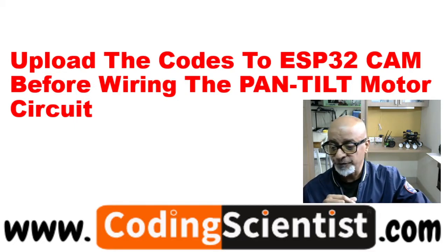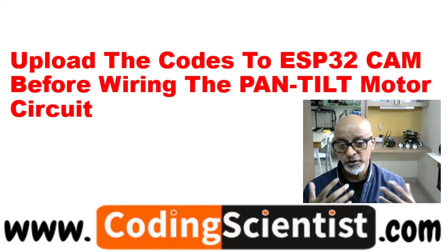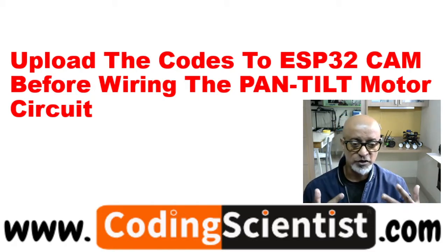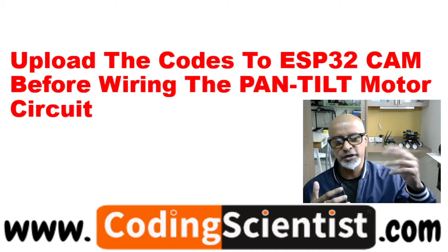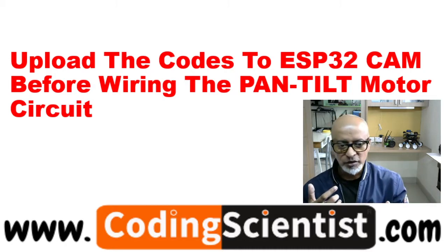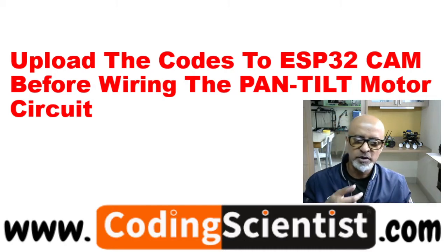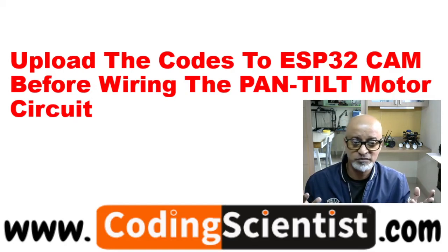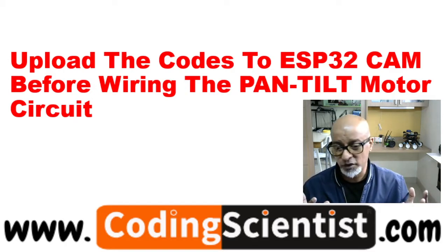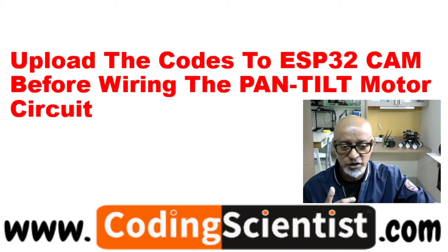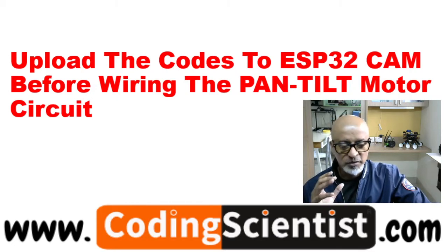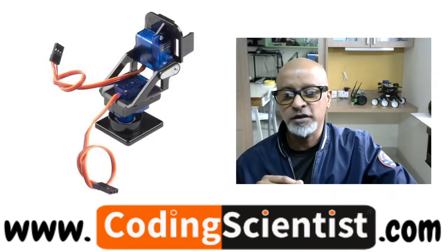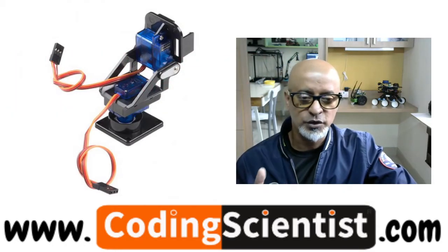All right. The reason is, of course, we will be using two different GPIO pins of the ESP32 CAM to connect your motors. And once you fix it and mount it, you may not be able to reset. That's another challenge, because the reset button is at the bottom of the ESP32 CAM board, which, as per design, is definitely not good, but can't help. That's how it is. So that's the reason. Go ahead and load the code first, and then come back to the circuit, which is what I will show you in the next slide.